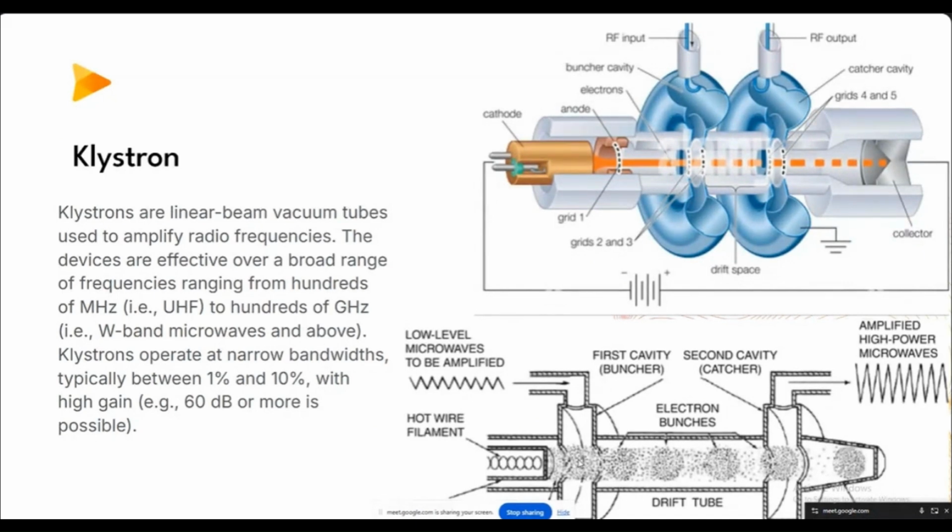And then when those electrons have equal energies, they accumulate here, and then there is a gap, and then there is another accumulation, and this keeps on going. When they reach here again, because of their energy, they strike here and create the same frequency RF wave, because they were oscillating here with a given frequency. So they will travel, and then oscillate here again and create an amplified RF wave. So the RF wave which was fed inside is now amplified.